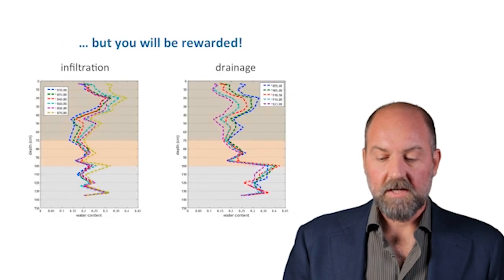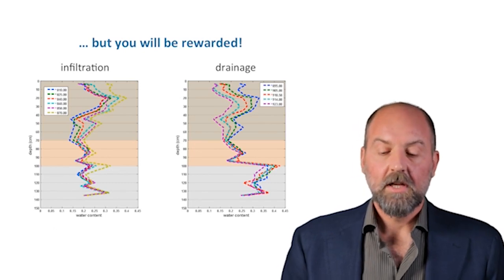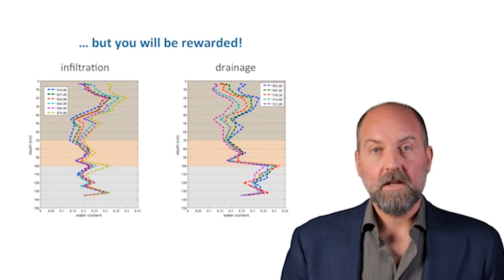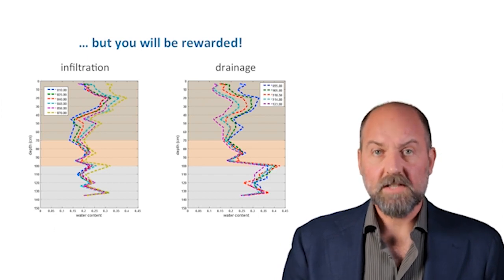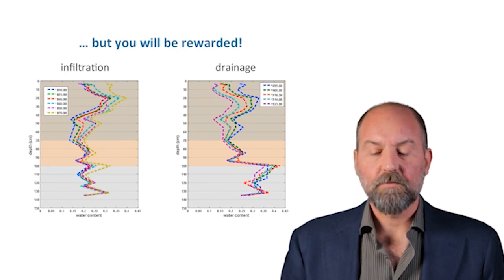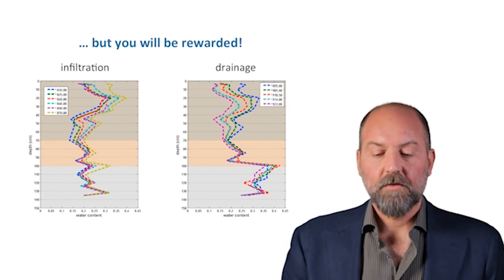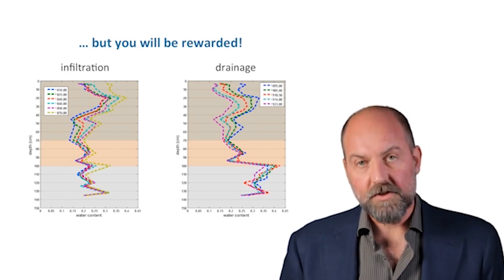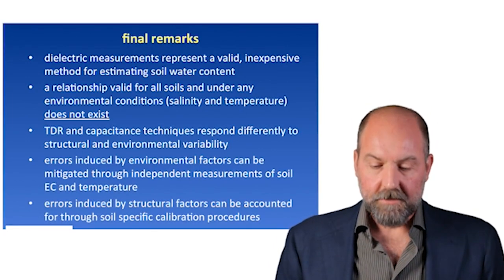We were trying to assess the performance of a capillary barrier on a landfill, and with the proper setup, and of course this is a rather expensive setup because we were featuring about 29 sensors from surface to about 2 meters, we were successful in monitoring the very movement of water through the soil layer and eventually through the capillary barrier. And this makes it for today.